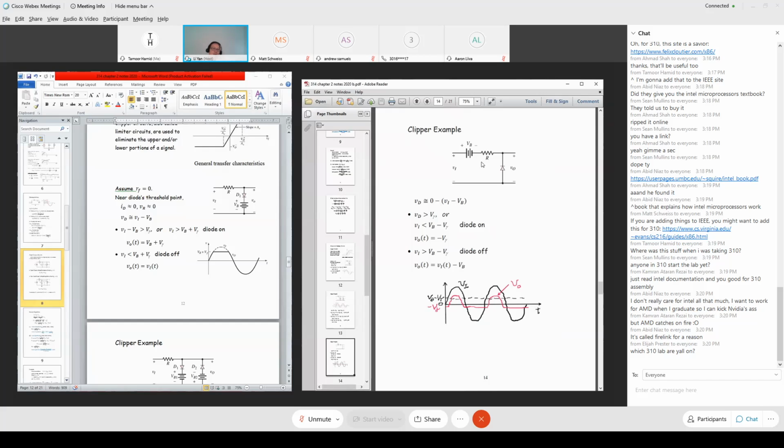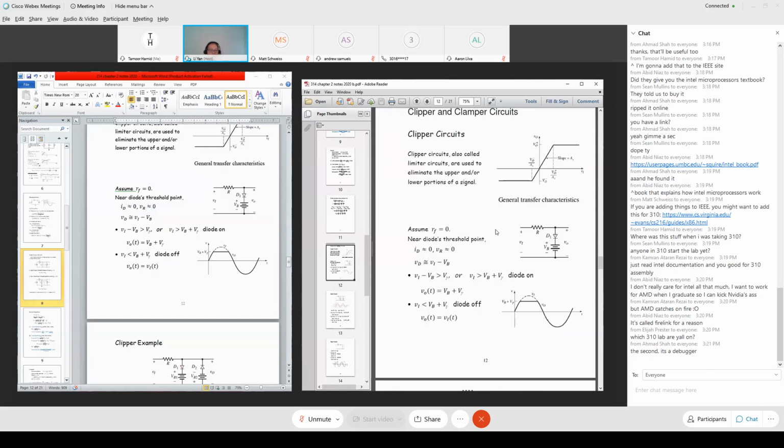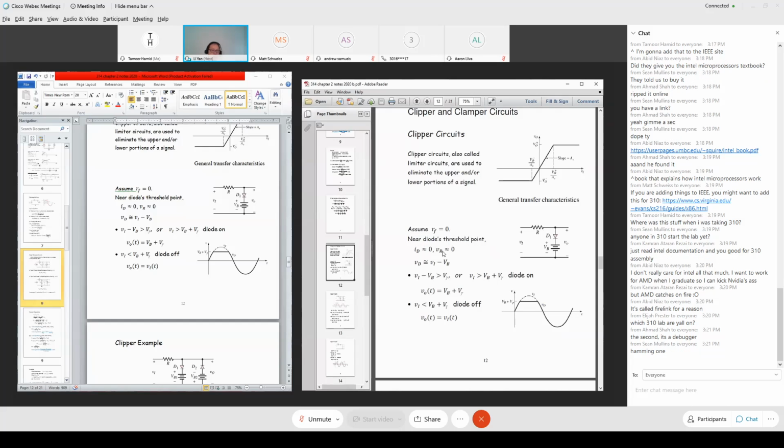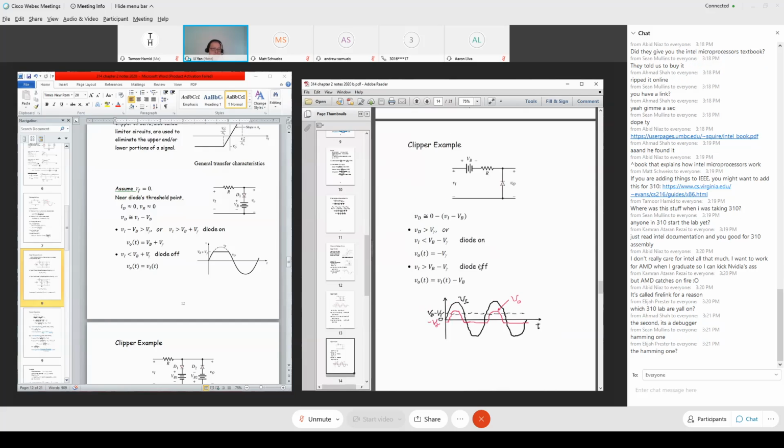You may ask, do you have to consider the voltage drop at the resistance? Well, my claim is that near the threshold point, I neglect that. It's an approximation. Remember always, near the diode's threshold point, the diode current is negligibly small, so the voltage drop at the resistance can be neglected. This simplifies the analysis at the critical point. So at the critical point, the diode voltage is given by this expression.